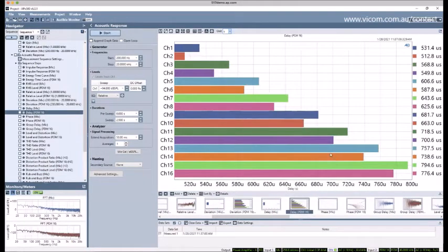And you can actually see two things here that are a little bit interesting. The first is what we expect, which is that the delay increases as the microphones at the back of the array relative to the signal source are further away. The other thing is actually there's a little defect on this board. The data lines were inverted.